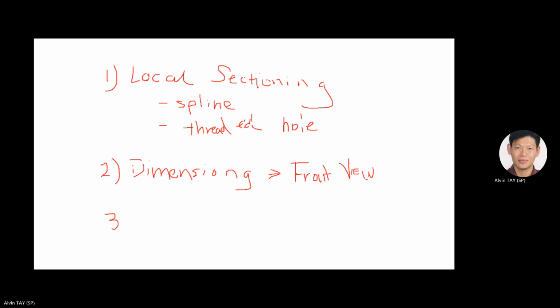Number 3 is your sectioning. Okay. Sectioning. You must know, because it's an assembled view, what to section, also know what you hatch and what not to hatch. Okay. So if you hatch wrongly, you are going to lose marks. You don't get minus marks per se, so you really just don't get the marks. Okay. Alright, so just take note of this. Right? Main thing is your hatching. Okay, whether you should hatch or not hatch.